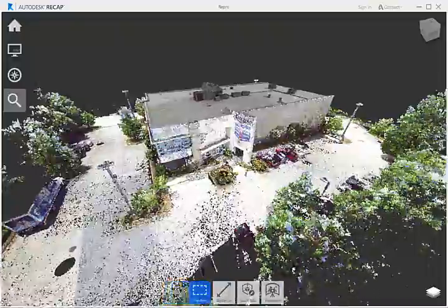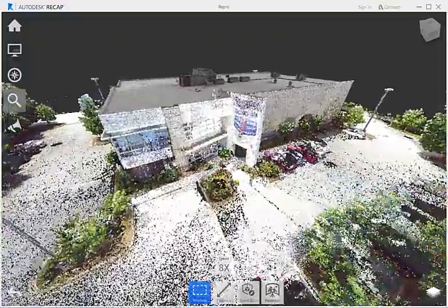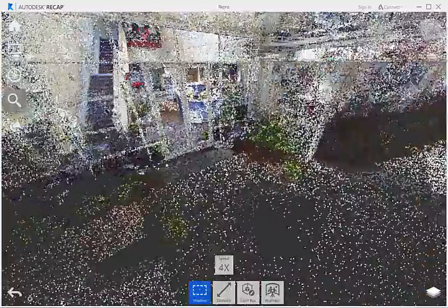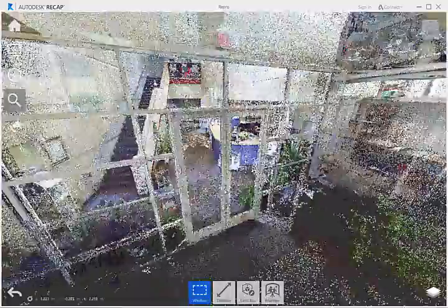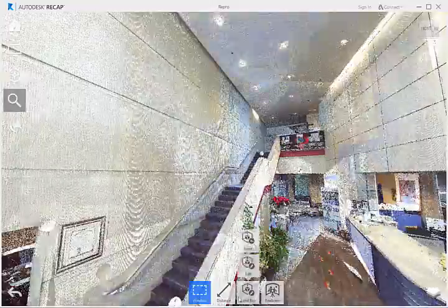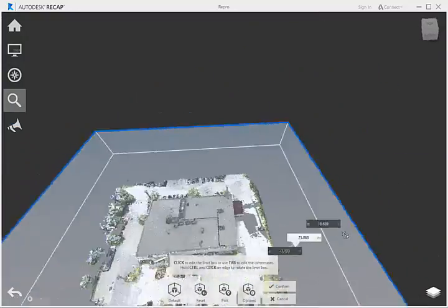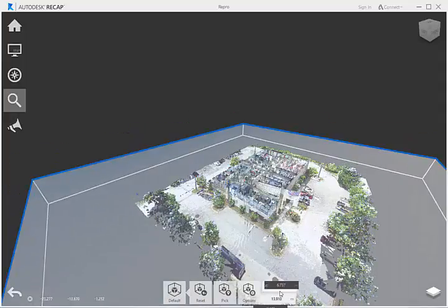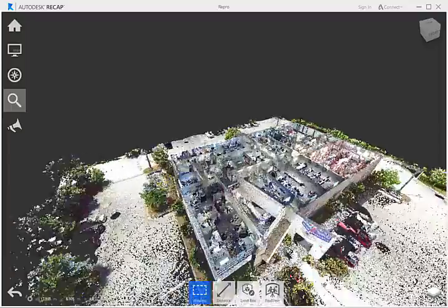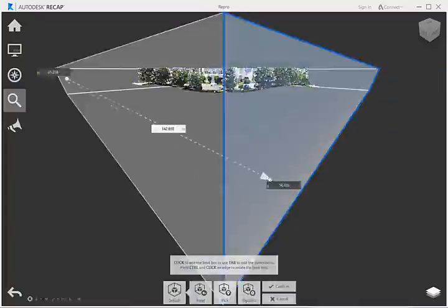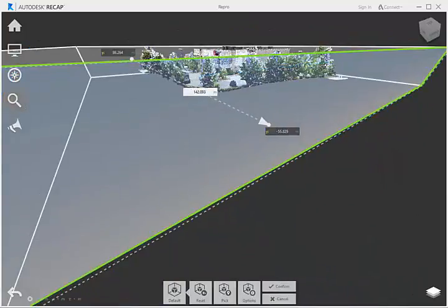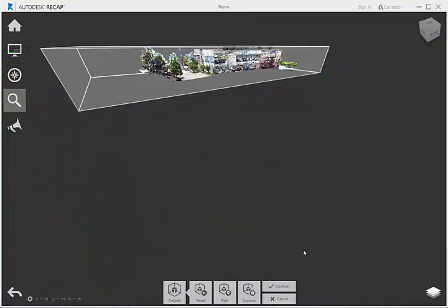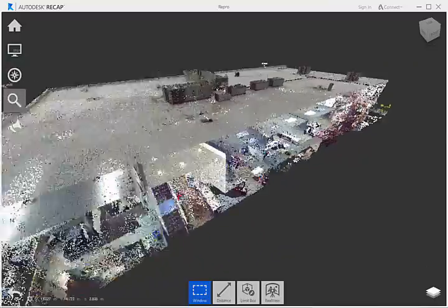When using any of the Autodesk products, we will bring the point cloud into Autodesk Recap. Recap is a high-performance point cloud visualization engine that is not only a standalone application, but is also built into many of the Autodesk design suites. We can use the Recap application to view and navigate the point cloud. By cutting sections of the data, we can view the model in ways that would otherwise be difficult using data collected with traditional means of as-built surveying and measuring. Here, we are cutting a cross-section to view the floor-to-floor relationships and to determine the distance between the floors. We can get an understanding of the interstitial spaces and the ceiling plenums.